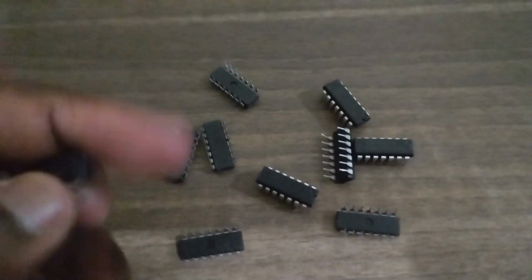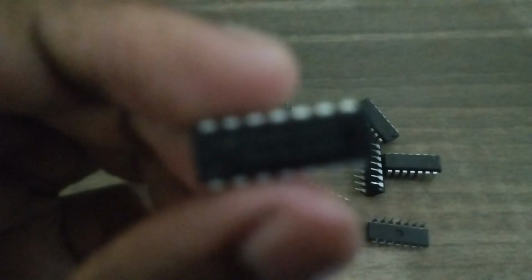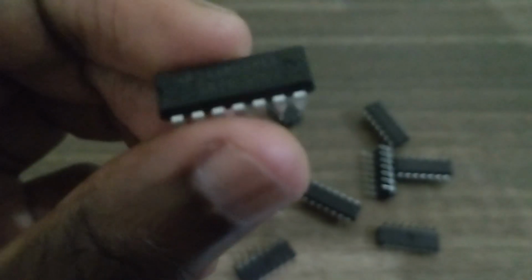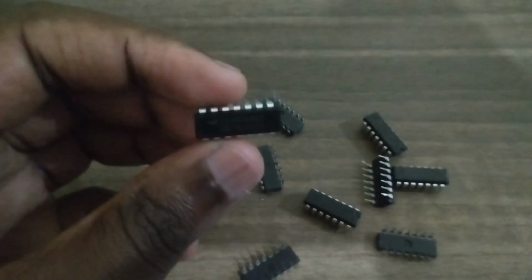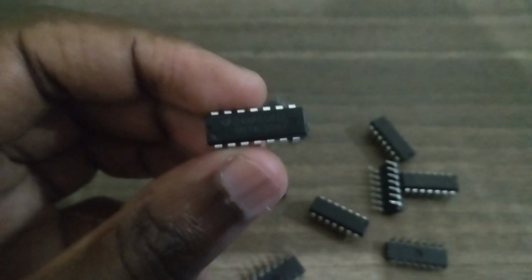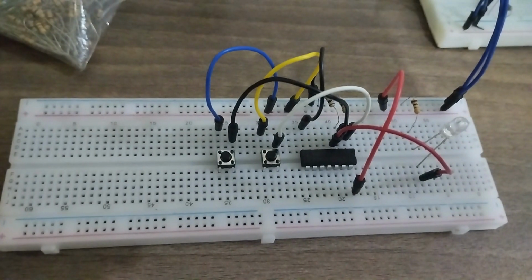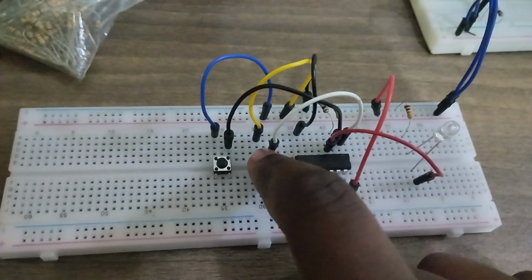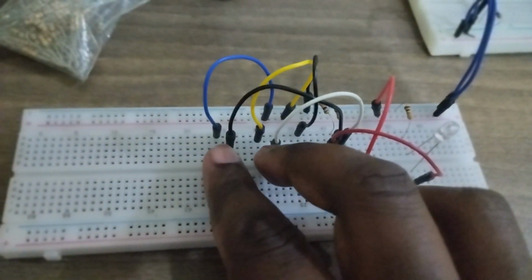These are some integrated circuits I had bought online. Specifically, these are the 74LS08, which are the quad AND gate. So this IC contains 4 AND gates inside. I'll use them to create an AND gate instead of using the transistors as we had done earlier. I can wire them according to the pinout we had seen earlier. I've connected them on a breadboard and I used the pinout to decide which gate to use. I've used only one of the gates, and you can see that it lights only when I press both of the buttons. So it works.